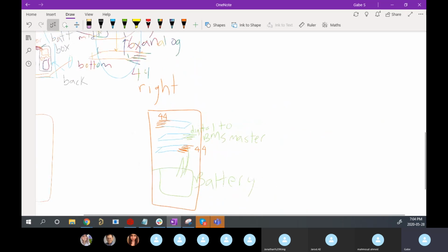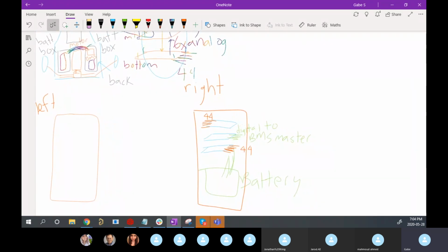But now how do we measure temperature of the other box? Well, you guys suck it up and go for it, right? Send 44 analog signals across to measure the temperatures of this battery, right? That's a lot of wires, first of all. You want to minimize the number of wires like in your harness, because that's just a huge amount. First of all, of weight. Second of all, it's just really hard to work with in the car.